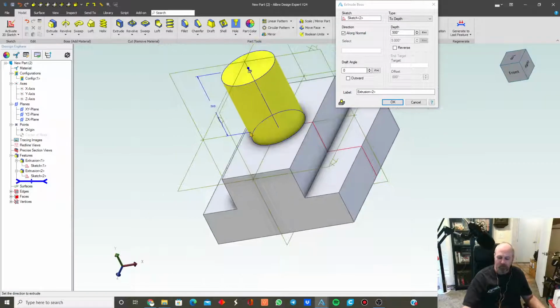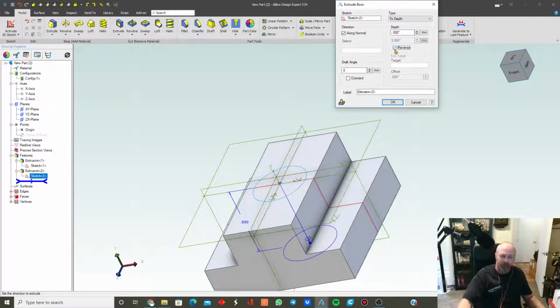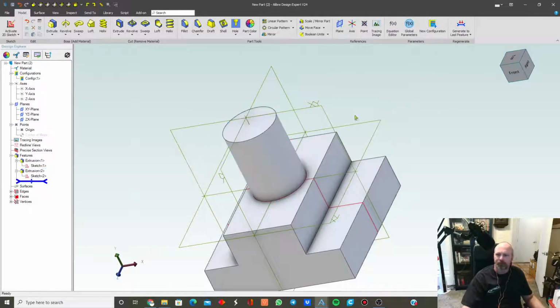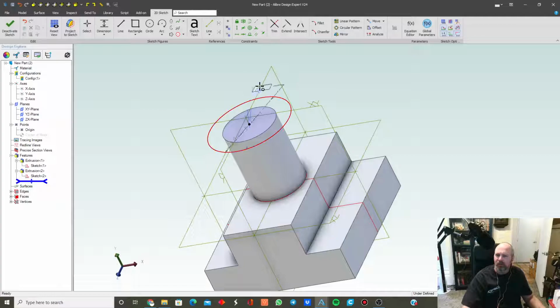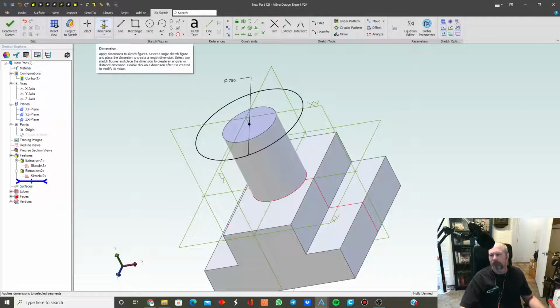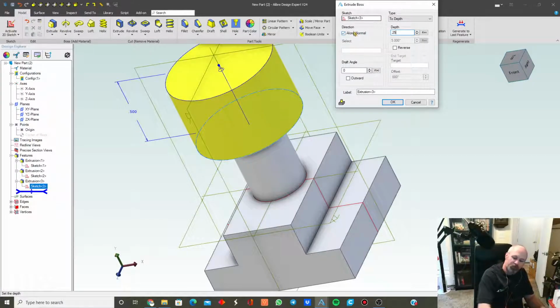If you look at it, see how it grows up 5 inches. You can adjust it up and down. You can actually make it reverse so it'll drop down into the part, depending on what you're trying to pull off. So bring that up, hit the top of that again, activate the sketch again, circle. I'm going to put a button on the top of it and dimension that at 3/4 of an inch, 0.75. Then deactivate, extrude, let's make that 0.25 tall.